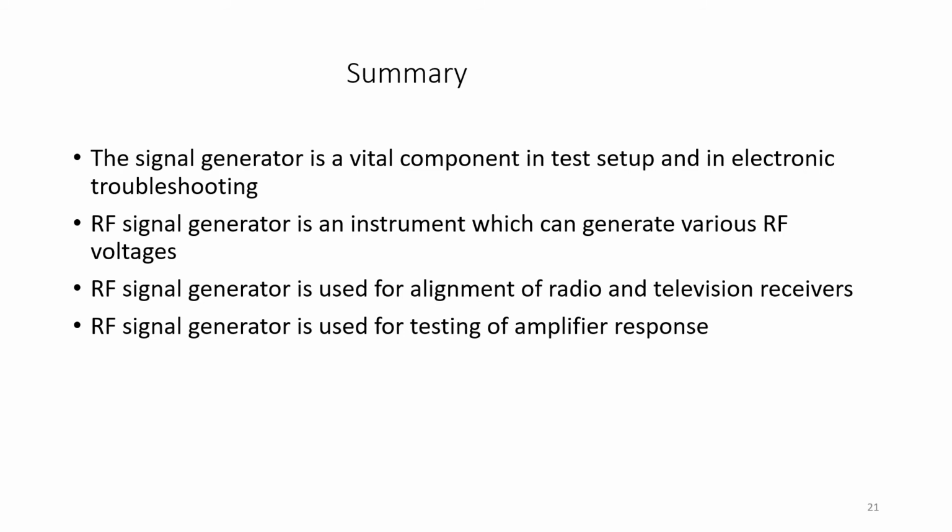As I have told you, in the block diagram we have seen the shielding. The radio frequency leakage from a signal generator can create practical difficulties in measuring receiver sensitivities, particularly if the receiver itself is not well shielded. Additionally, inaccuracies in attenuation at the microvolt level may result if strong radiation fields exist.